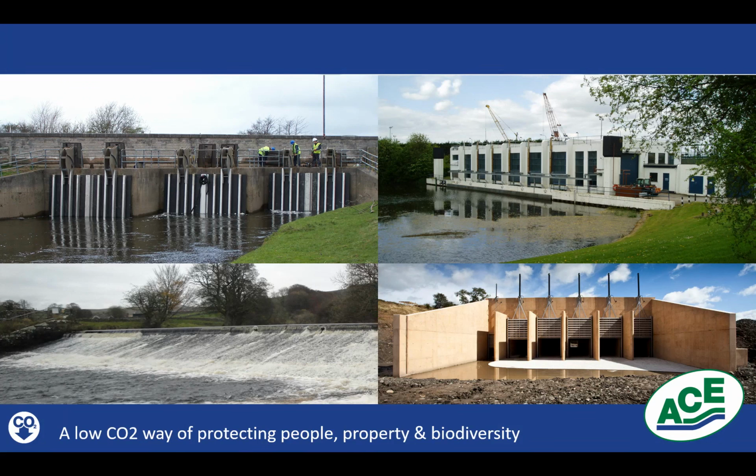Although they got put in usually for whether that be creating energy for textile production in the past, for example, or distilleries up in Scotland to tap water off. They've always been used as a source of energy. However, once they've been built and established, especially for a few hundred years, quite frequently you just can't remove them because of the impact that the flooding could have downstream if you were to do so. So they become intricate and part of the river system, which unfortunately a lot of the time means that you can't get rid of these weirs anymore.